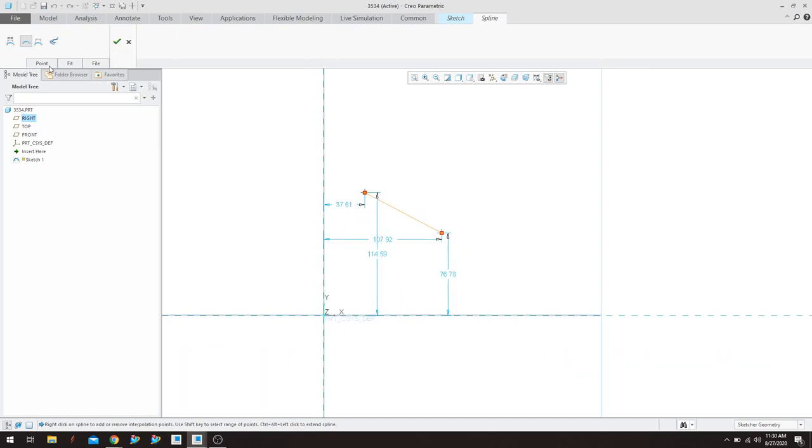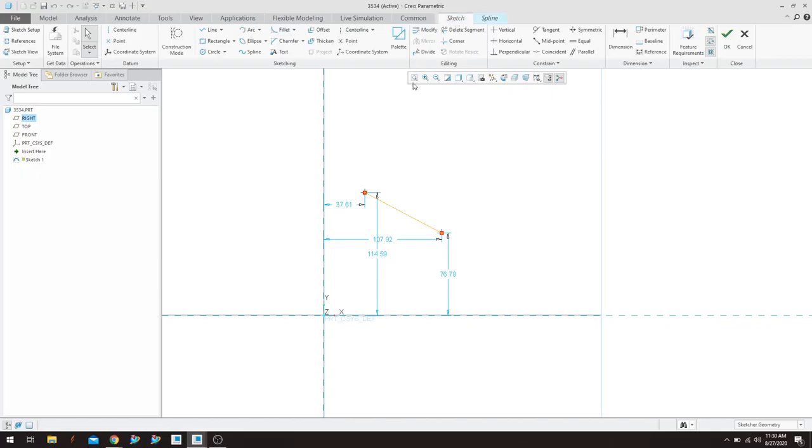So if you want to import a certain amount of points into the sketcher, you need to create a coordinate system. You cannot use the coordinate system that's located here. You must create one within the sketcher. So I'm going to go ahead and go back into the sketch here, this tab. And then I'm going to come over here and choose the coordinate system located there.